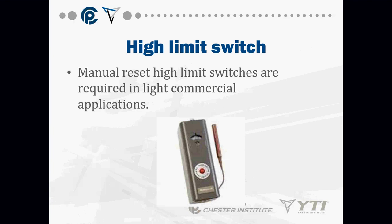If the boiler water gets below, say, 120 degrees, it's going to turn the burner back on to heat the boiler back up to, we'll say, 160 degrees, and then shut off. Okay, they're maintaining a boiler temperature so that we're not constantly running a cold boiler, or what we would call a cold start. Which obviously helps with energy efficiency and fuel consumption.